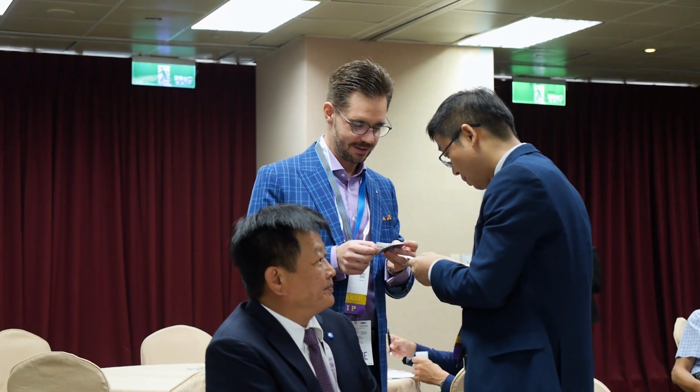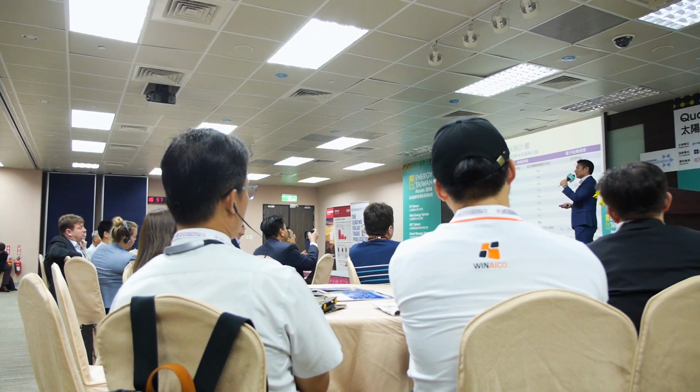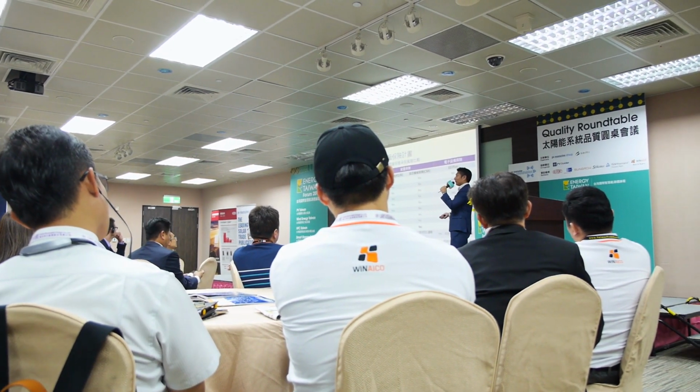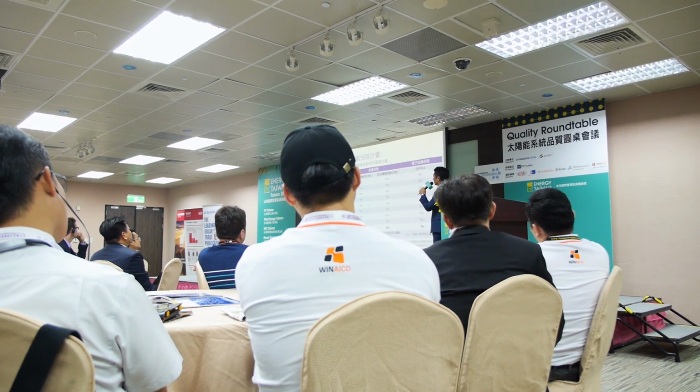Let's say as an investor, if I want to compare different backsheets, what tests do you recommend to see whether a backsheet fails or does not fail for floating PV? So for floating PV, if we consider testing methods like increased UV, increased thermal cycling, and increased dynamic load testing, Tedlar is still maybe the best or even the only one that can pass all of these upgraded requirements.